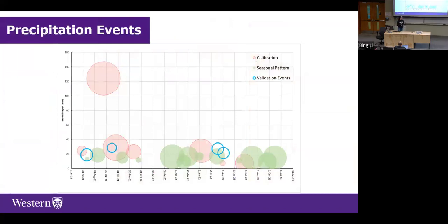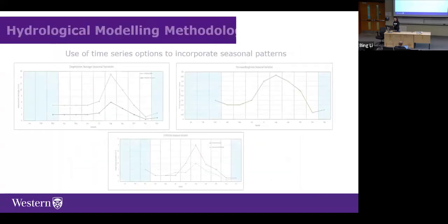The precipitation events that I used for the event-based model vary. This graph shows the different types of events I used, which ranged in rainfall depth. I tried to capture the larger events, as those are estimated to contribute larger loads in general. For the seasonal pattern that I incorporated, I had to use a lot of events for the different months. So far I haven't incorporated snowfall and snowmelt, which is a major aspect of the cold climate model, and that's something I have to do as well.